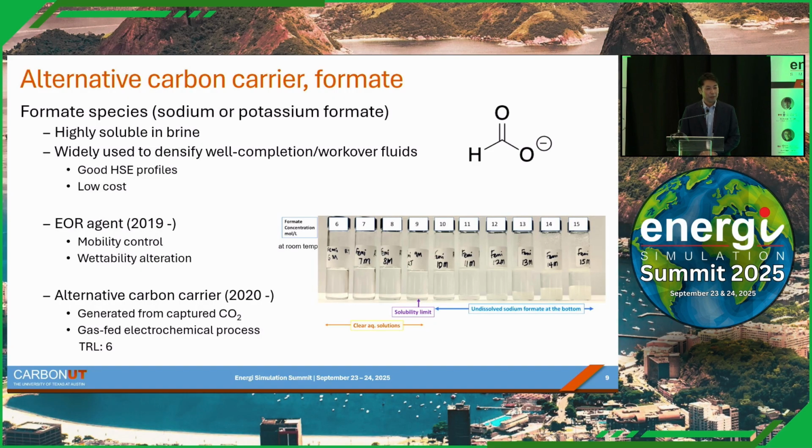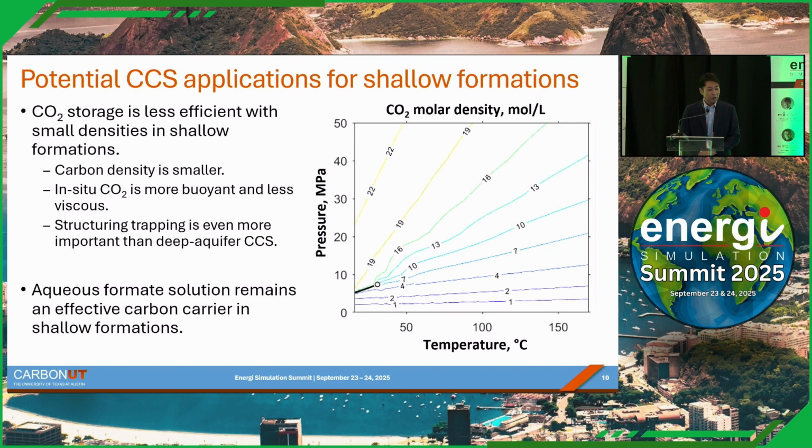And we studied EOR application of sodium formate solution for mobility control and wettability alteration. And also we have studied CO2 capture and conversion into formate species using an electrochemical process in our research group. And currently this technology is rated at a TRL of 6. And some sponsors are interested in application of formate-based CCS, especially for shallow formations, because this is where CO2 density is low. Therefore, CO2 is subject to more buoyant forces and has lower viscosity, increasing the mobility.